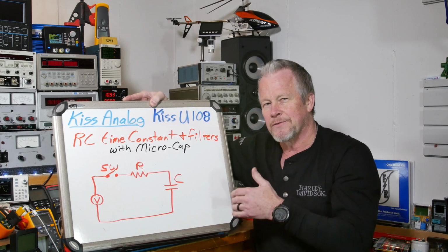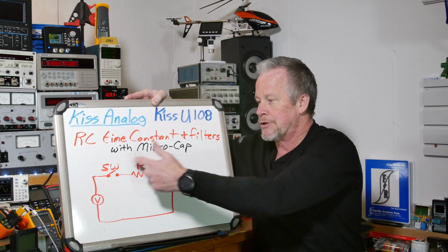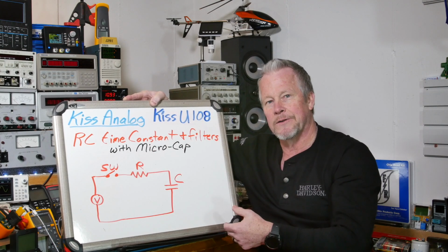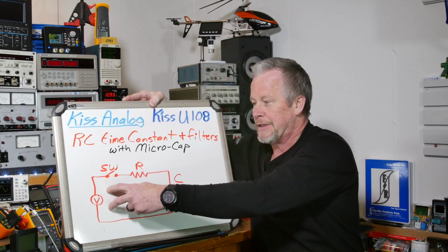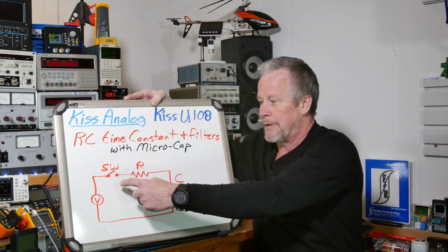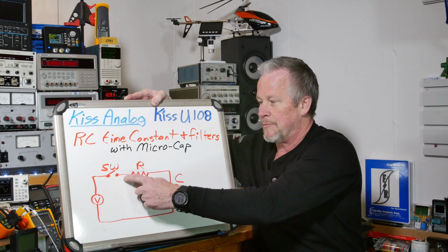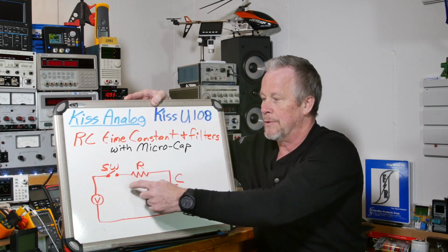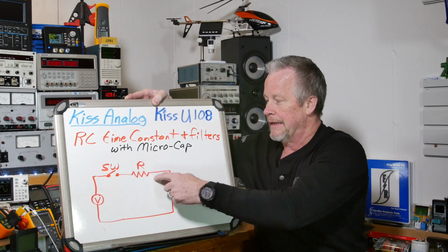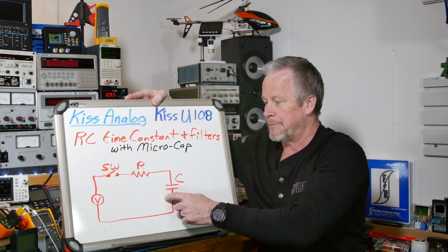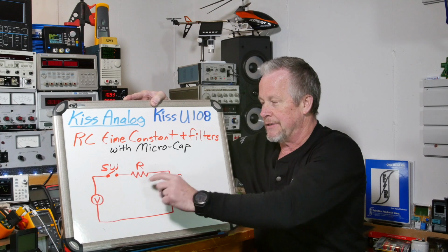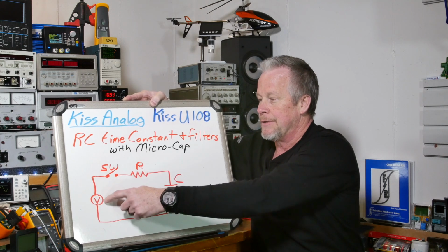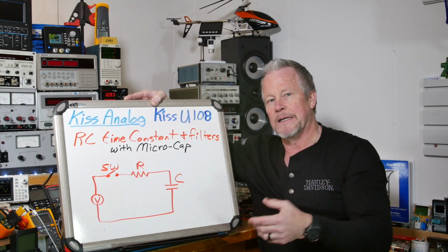There's Kirchhoff's voltage law: all voltages around a loop will equal 0. So you have a plus voltage here, but if current's flowing this way, you'll have a plus sign here, and so this voltage drop will cancel with that one. Then current comes this way, you get plus, minus. So these two guys are in series. The voltage drops on these two add up, subtract from that, and you end up at 0.